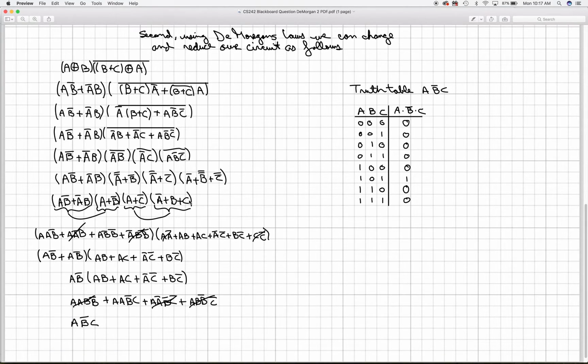Okay, so what we can do then is take this part, again using DeMorgan's rule, so we'll change the AND to an OR. This is going to be A NOT NOT, and this will be B NOT. And so that's this part over here. We'll change that AND to an OR operator, so this is going to be A NOT NOT, and then the NOT of C. And then finally, we'll take these AND operators, turn them into OR operators, and split these up. So that's going to be A NOT, B NOT NOT, you see that over here, C NOT NOT, you see that over here.